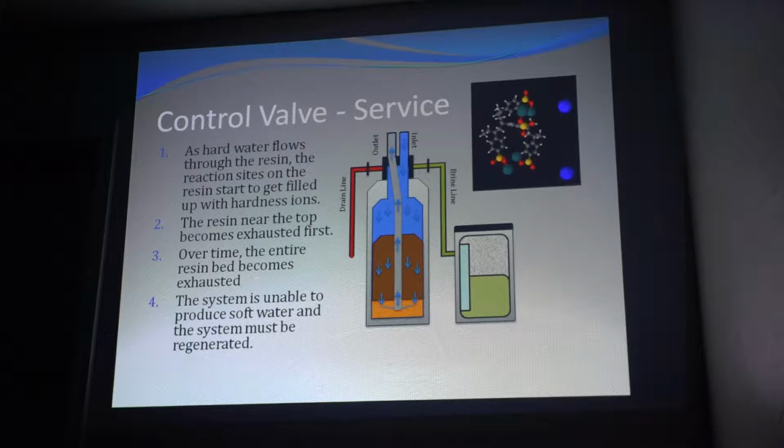Okay, so if you go out to a home and they have hard water and have been getting hard water, because even like at the cheese factory, the meter's probably plugged, they've been having hard water for 6 weeks. The softener hasn't regenerated. If you go in there and give it one regeneration, you're not going to bring it back to full capacity. It needs 2 back-to-back regenerations to bring it back to full capacity. If you don't do that, you're going to get another phone call.